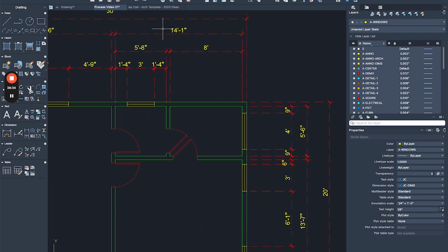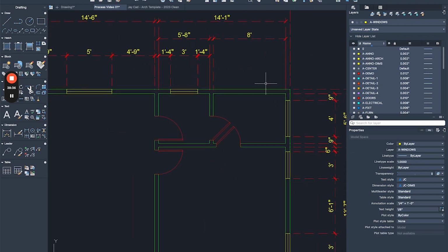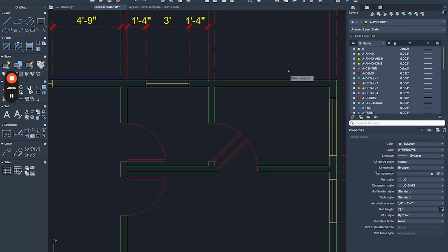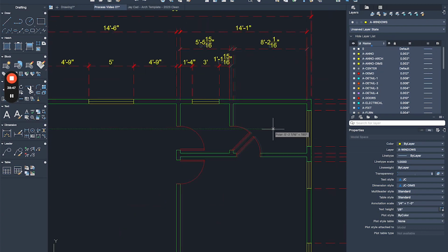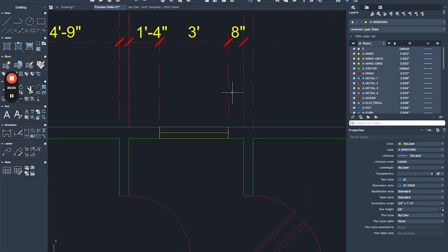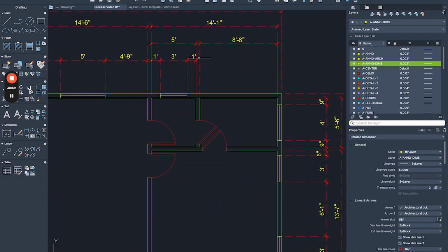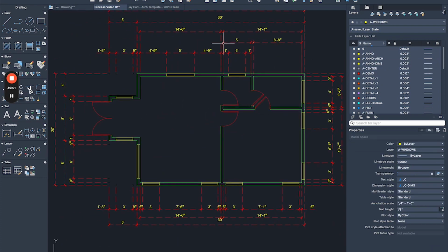Let's say he asks to make the laundry smaller and the bathroom bigger. So what I will do is I will come here, I will do a stretch. Let's say they would like us to add 8 inches from here to here. So I would literally do this entire stretch, go to the left by 8 inches. And then you need to modify the window. If you're trying to make it exactly in the middle, you want to modify the values. And now, this is our current design. So that's why I do things the way I'm doing them. And another save.